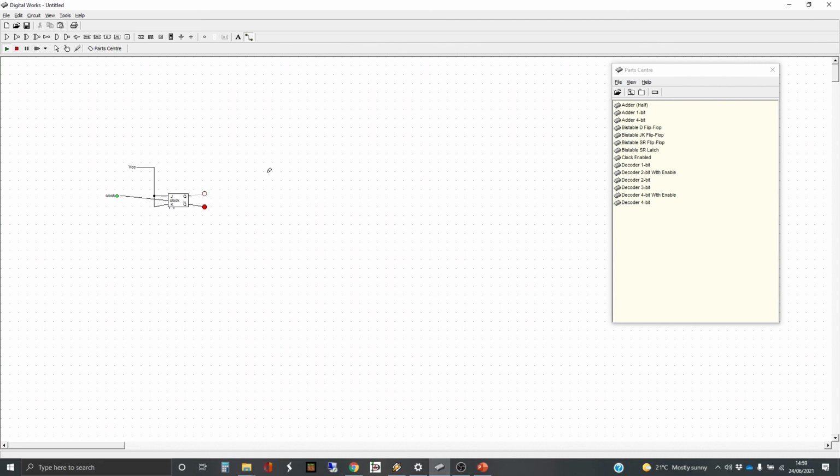If we just consider the clock and we don't look at the not Q output, to help us do that, I'm going to get rid of that there. You might notice that the clock is flashing at 1 cycle per second, and our Q here is flashing at half a cycle per second, or in other words, 1 cycle every 2 seconds.